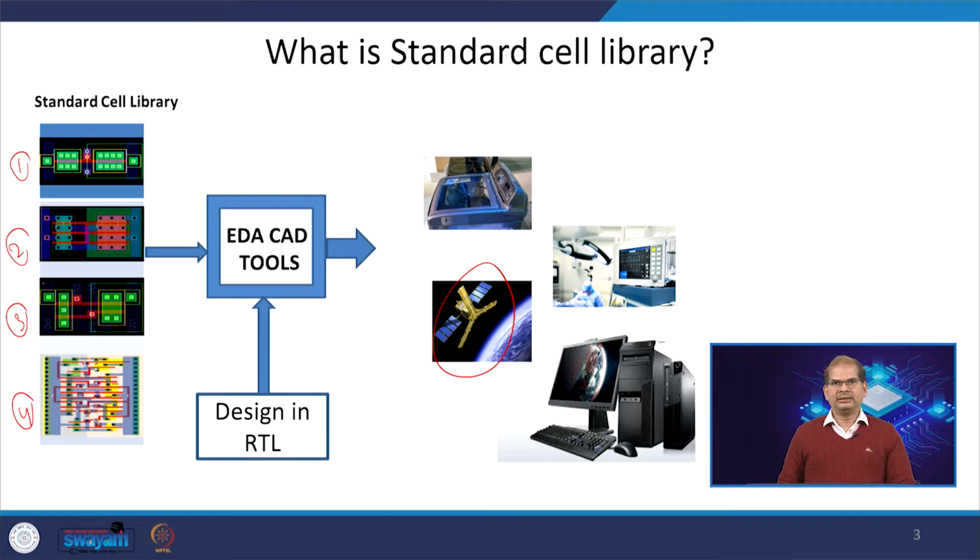So, this chip, the IC, is generated from the layouts, and layouts of the designs can be used in several places. One important point I want to make is that standard cells are the basic requirement of any kind of digital design. So, digital designs require this standard cell library. We have a well defined methodology for how the standard cells can be taken inside the EDA tools and combined with the RTL to create the actual required implementation at the chip level.